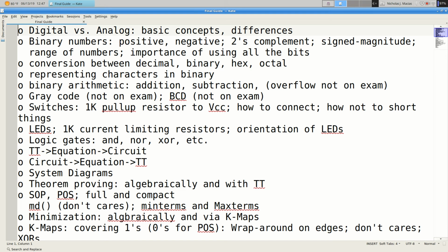The circuit analysis, you might start with a circuit, forget about the flip-flops here, right? Here's a circuit with 2 inputs and an output. And you can write an equation. Z0 equals the XOR of Q0 and Q1, so you get that. And then if you need to write a truth table, you can put combinations of your inputs and your output and so on. So we can go in either direction.